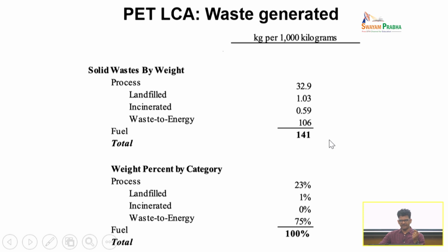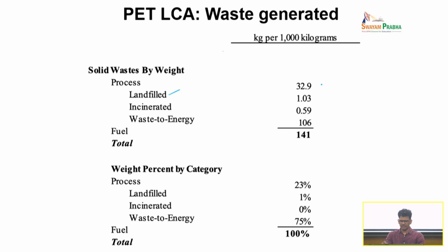The next thing is waste generated. Remember, this waste is not the waste generated because of the resin itself, but because to make the resin you are using material and some material is going to be wasted. It is not the plastic waste, it is the waste created to manufacture the resin. Here, the landfilled solid waste, also per 1000 kilograms of PET, is about 33 kilograms.